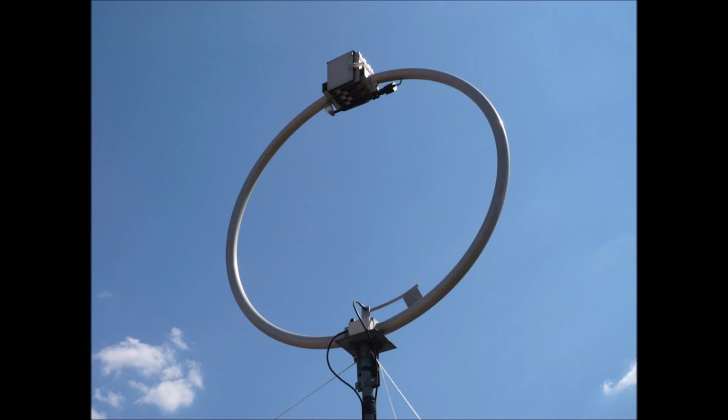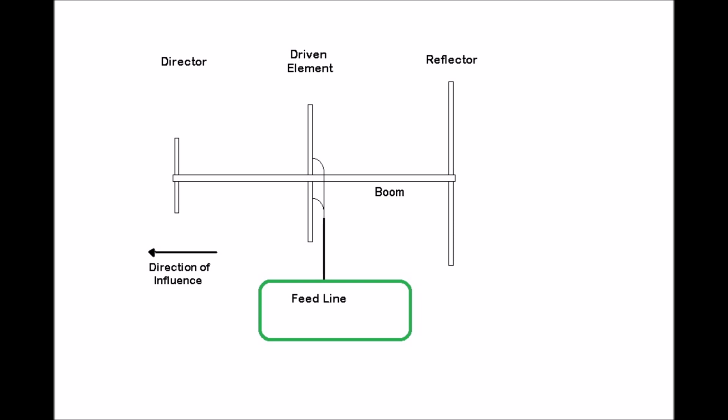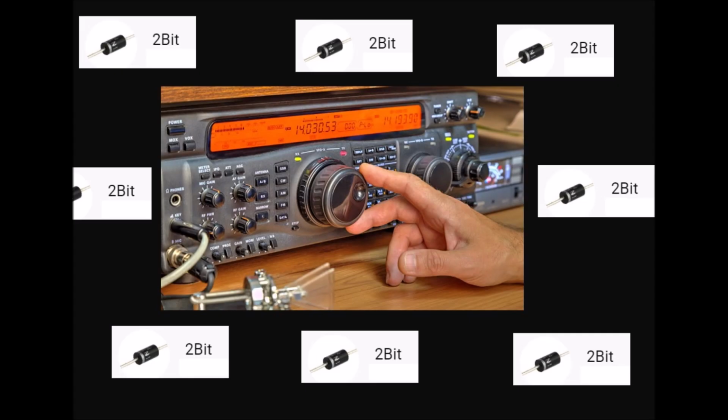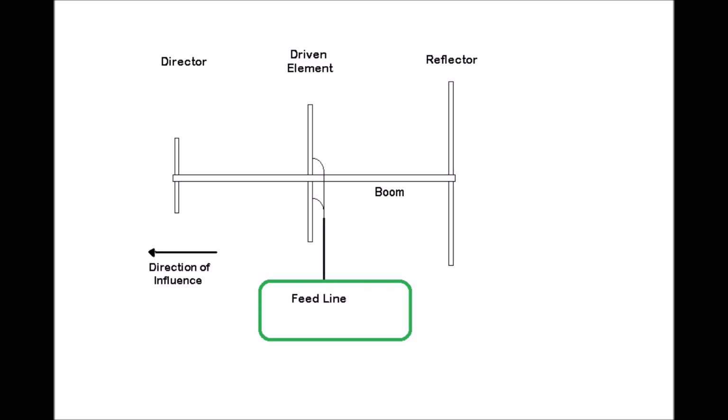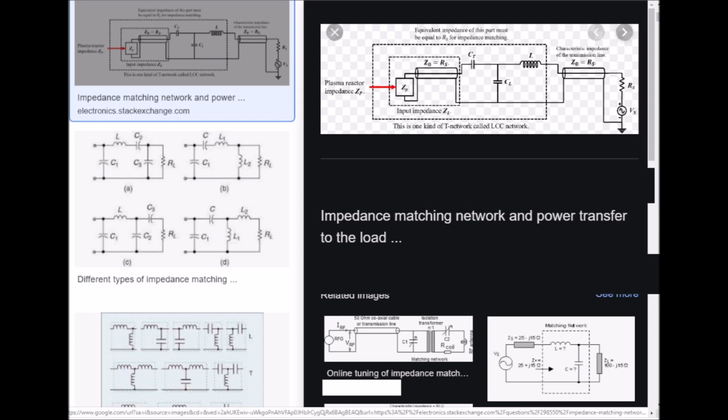An antenna lead-in is the transmission line or feed line, which connects the antenna to a transmitter or receiver. The antenna feed may refer to all components connecting the antenna to the transmitter or receiver, such as an impedance matching network in addition to the transmission line.